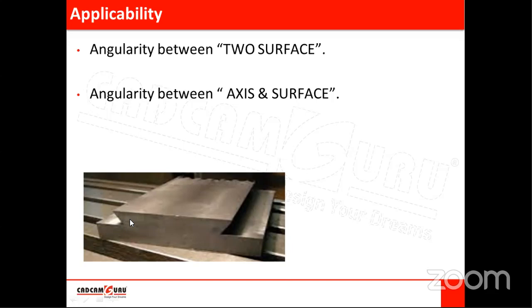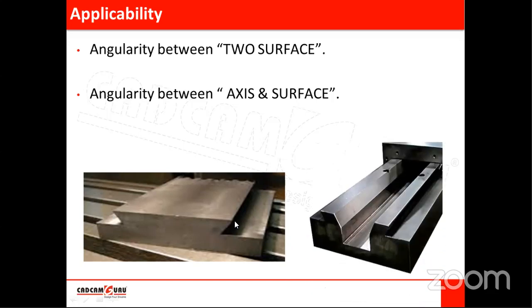Means a dovetail slot is provided in that bed, and these are called dovetail guides. Okay. So if you see, the assembly is not there, but the upper part which will get fitted on this is called the dovetail slot, and what is seen in this image is a dovetail guide. So that part will get fitted on this and it will slide along this lane.